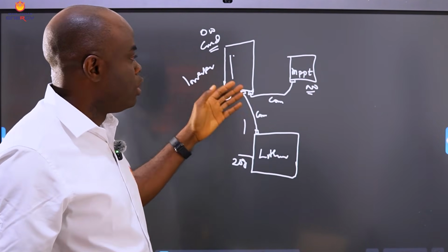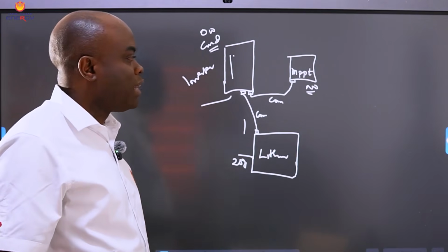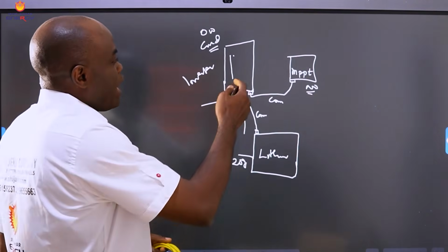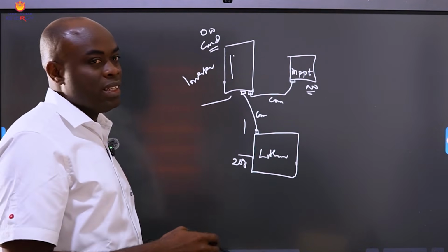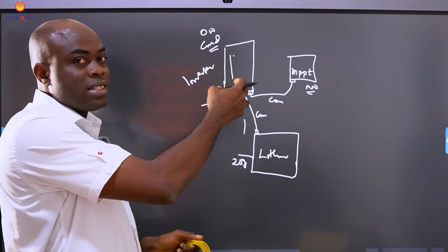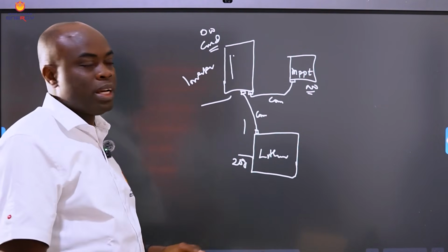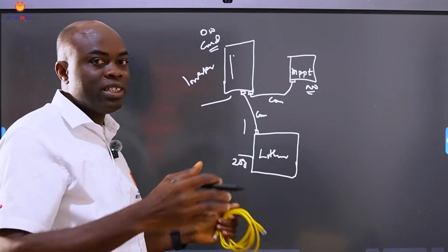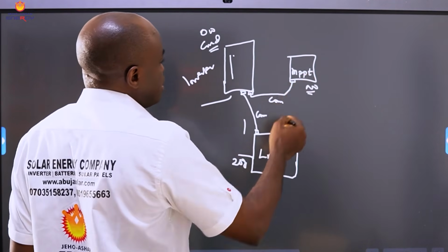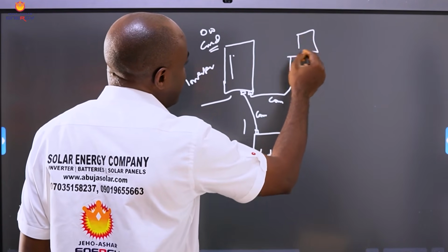And we also know, for example, you might install an inverter on the site. Most of the time, what I do is this: if I have an inverter and the solar power, based on the inverter capacity, is not sufficient to power my customer's load and also charge the battery bank I have, instead of getting an MPPT, I will just get a second inverter.